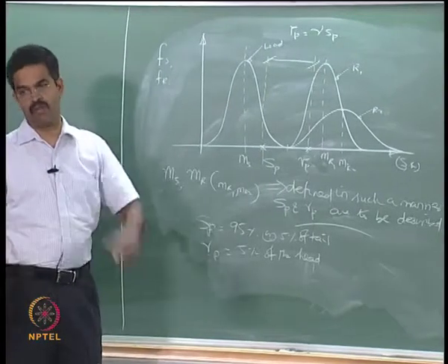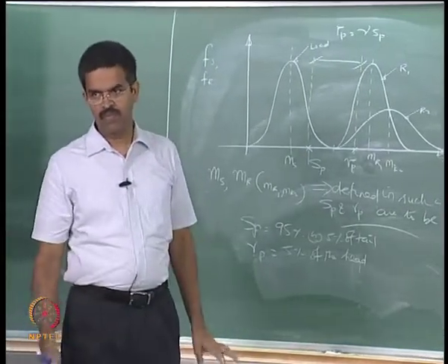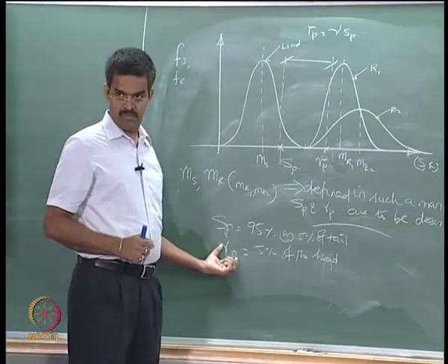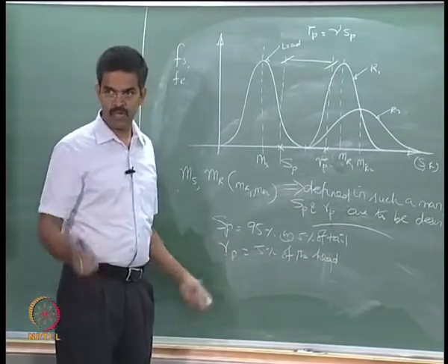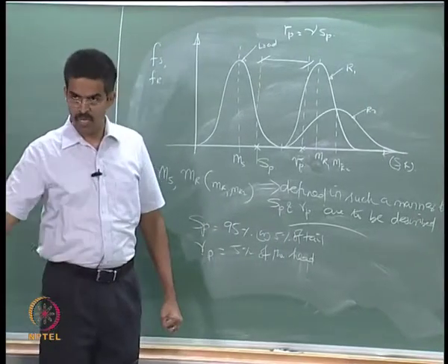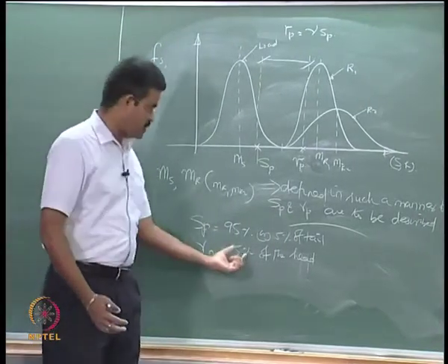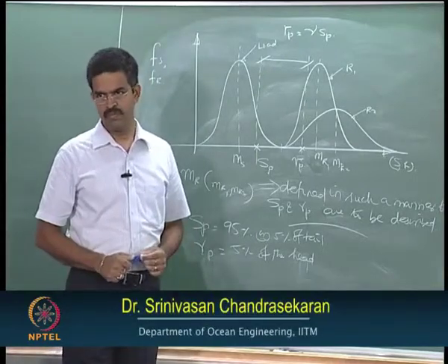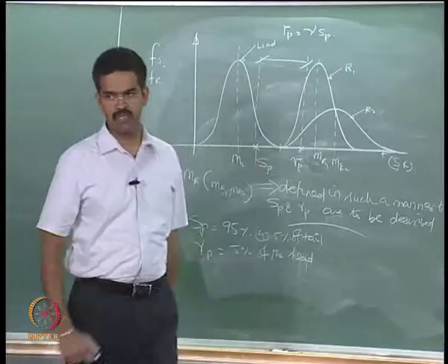So, that is the limit what we are talking about. Is that clear? For example, if you want to really qualify any material in terms of its Young's modulus, pick up the material, find the mean. If the mean is beyond 5% variation, reject it, and so on. Is that clear? We will continue this discussion in the next class.